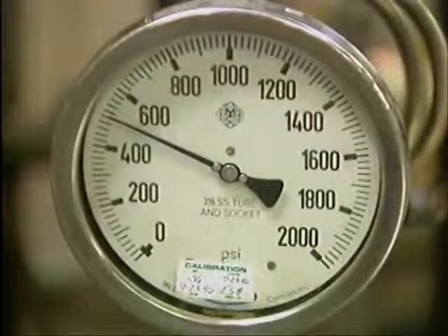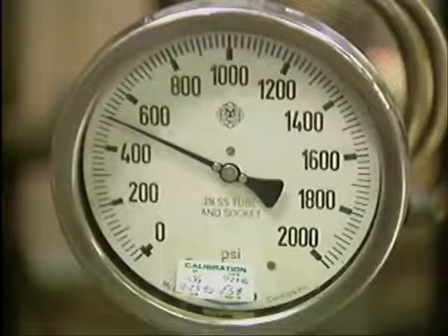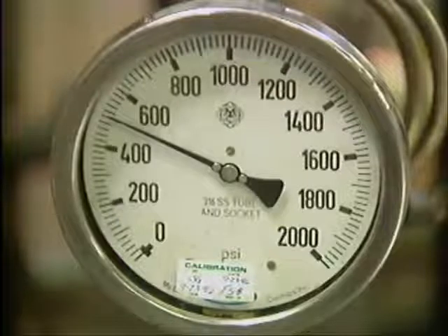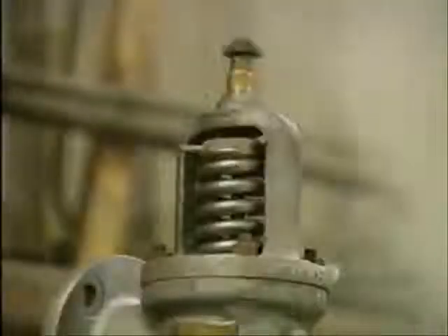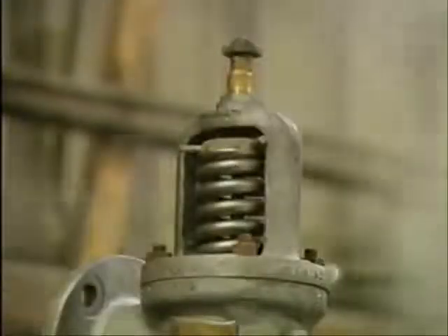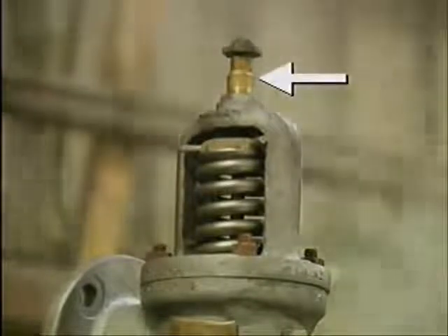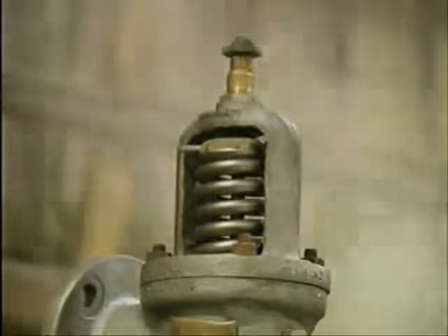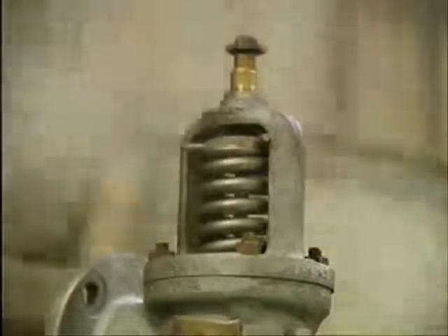The parts will then expand and contract at the same rate during the test. In any case, when you're testing popping pressure, you're checking whether the valve opens when it's supposed to. If it opens too soon or too late in relation to the valve's set point, you must make adjustments. For this Hudling chamber safety valve, you make set point adjustments by turning the compression screw. But before you can do that, you must lower the pressure so that there's no chance of the valves opening accidentally while you're working on it.